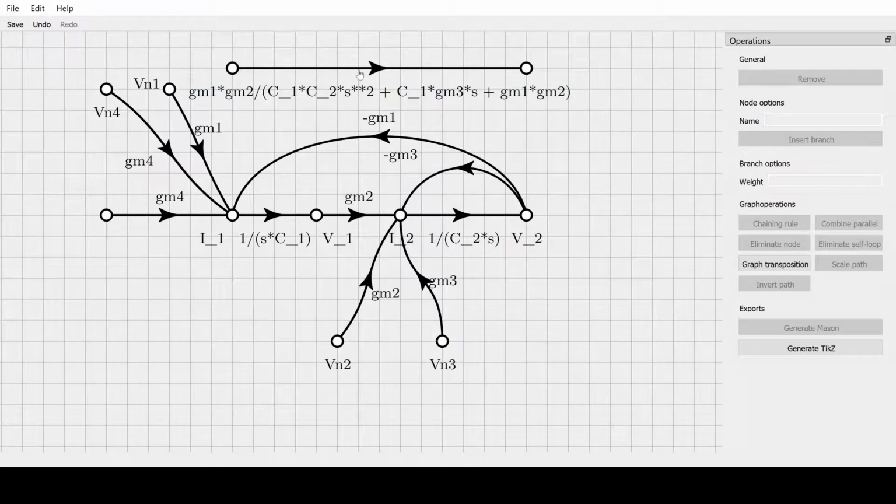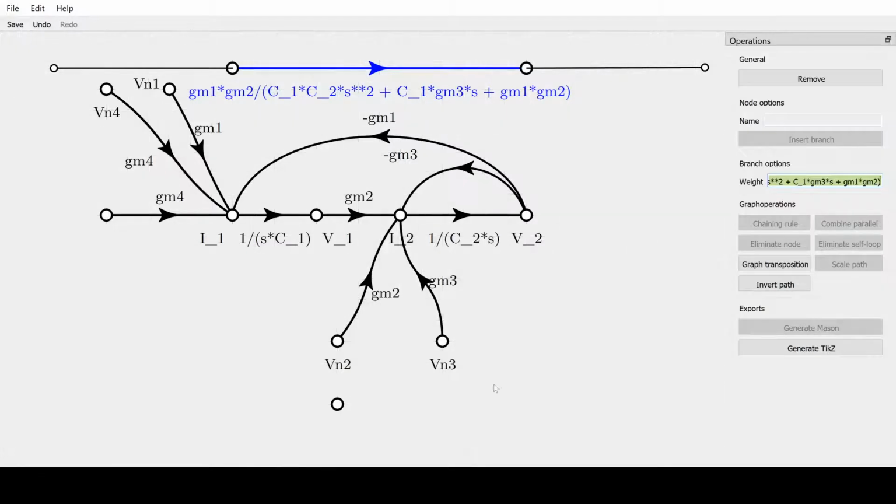Because it is the same as from the circuit input. So why did we bother? It is just a low-pass filter, but not both noise sources will have exactly the same forward gain. One has the GM4 in it, like the main filter, and the other a GM1 instead of a GM4. It is a totally different question about going from VN2 to the output.